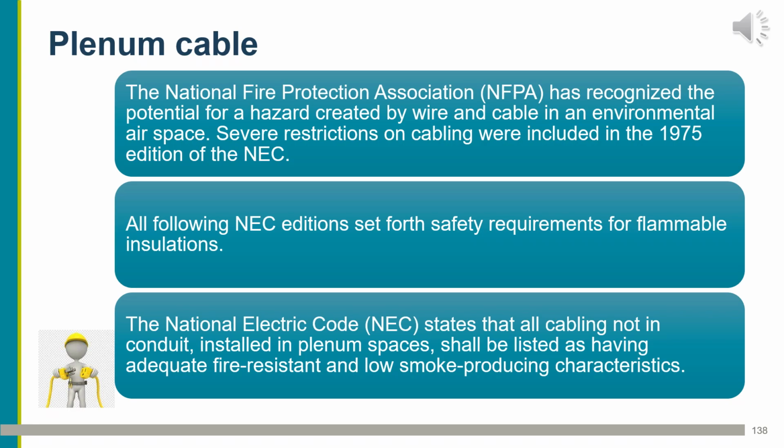So let's talk a little bit about a unique situation. That's plenum cable. The National Fire Protection Association, NFPA, has recognized the potential of a hazard that's created by wire and cable in an environmental airspace. All following NEC editions have requirements for this.